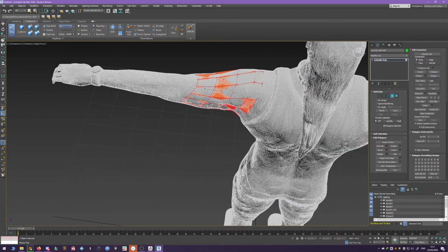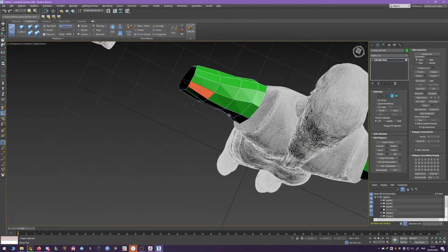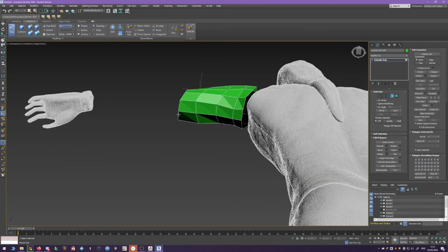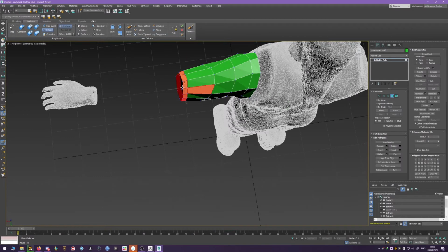You're going to want to move the vertices around the areas which bend to make them flow nicer. To see your loop clearly, you can simply hide the object which your surface snaps to and work on it like that. Keep the loop straight and try to have it placed in the direction of travel. Once you fix the loop around the elbow, you can keep extending it and the polygons will flow nicely.